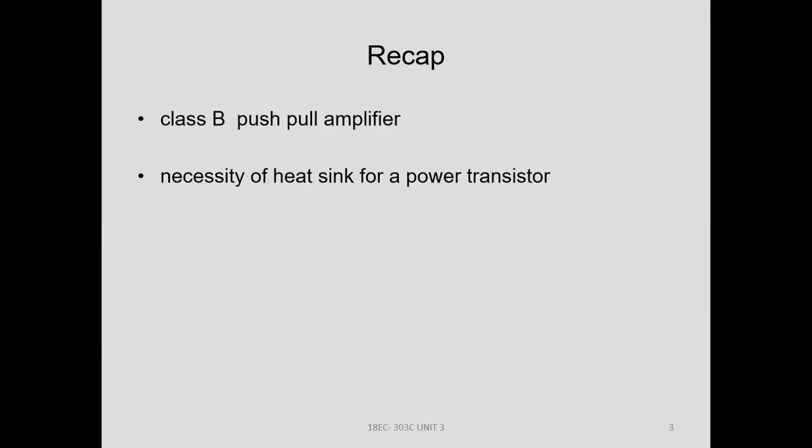What is the need of a heat sink in power transistors? Generally, the power dissipation is more in power transistors. To control that heat, that means to absorb that heat, additional devices are used. Those devices are called heat sinks. Generally, these devices are metal, black in color, and cooling is done by increasing the surface area. This is about the heat sink.